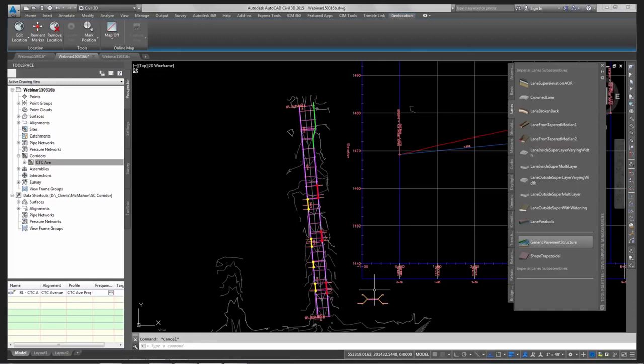Another question is, can you show me one that has a corner intersection with different parking stripe widths? One is a 6-foot and the other is a 10-foot. With conditionals, that would be a horizontal target, and what I would do is target one line that's 6 foot away, and then when the parking widths become 10 foot, I would then target a 10-foot line, and if it transitions from the 6 to the 10, just draw your polyline in that transition area.